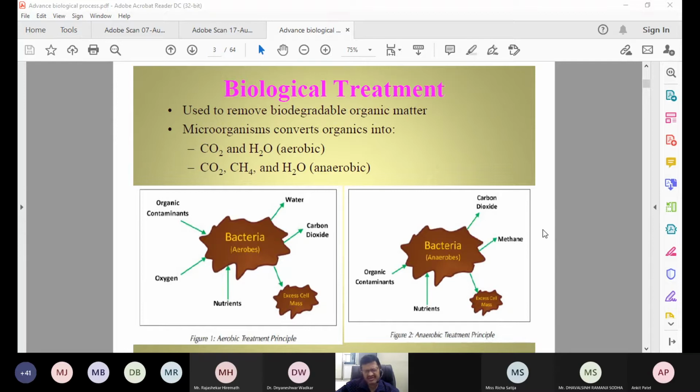final DO, you know. Let us say the initial DO is 8 milligram per liter. In one bottle the final DO is 5 milligram per liter, and in another bottle the final DO is 3 milligram per liter.